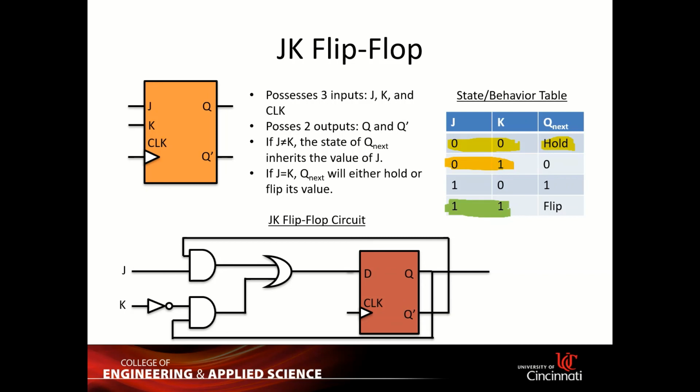Okay, and I also have other input combinations, which I will highlight in a different color quickly. So for 0 and 1, or 1 and 0. The difference of this input combination is that the state of Q doesn't depend on the previous state of Q. When you give the complementary input combination, the state of Q will be defined by a fixed number.